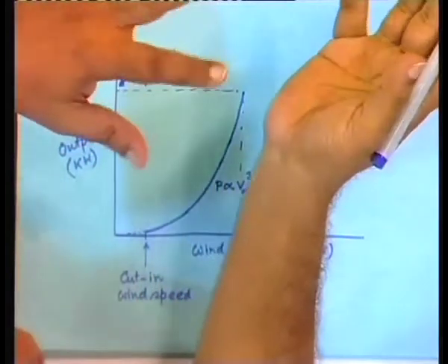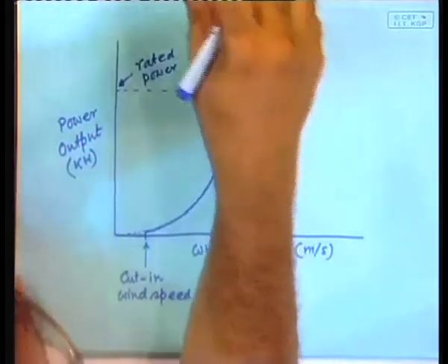When you did your laboratory experiments, you found that every machine has a nameplate, and on that nameplate a rated power is written. What does it mean? Can't it produce less than that? Yes, of course it can produce less than that. But if it produces more than that, then the wires overheat, they may burn, the insulation may go. So, overheating will not be desirable. So, that is the concept of the rated power. It comfortably works at that particular speed and particular power.